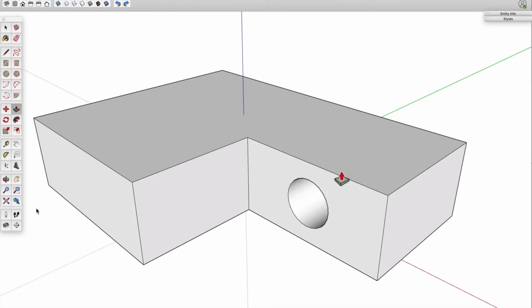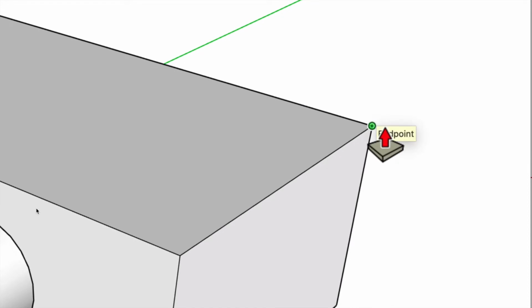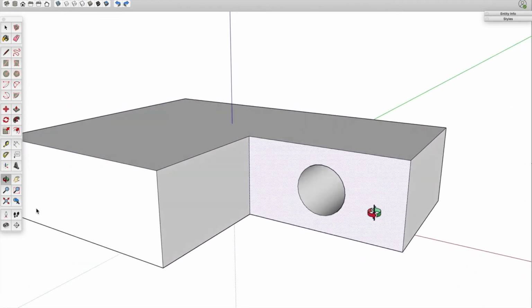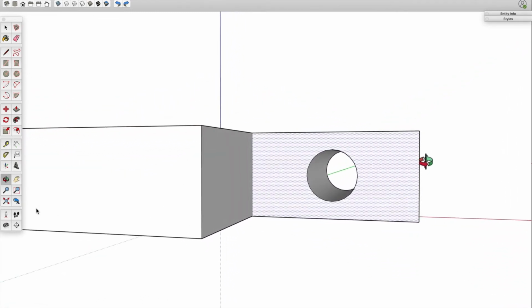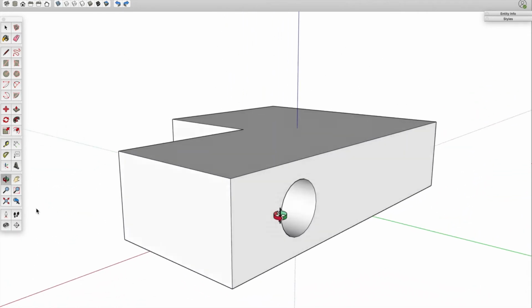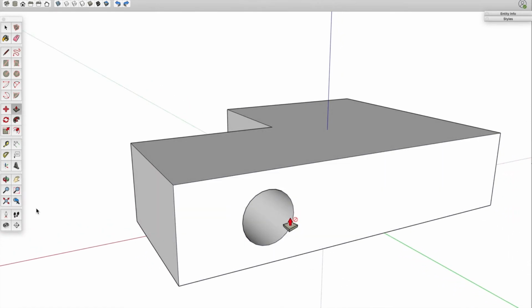So how do we get a tunnel that ends on the other side? Well, you can move your cursor over to this outside corner endpoint to infer it and click on it. That finishes your push-pull through to the other side. And as we know, this flat surface, when push-pulled to the other flat surface, if you go ahead and orbit now, it canceled it out. So now you can see through, or if you orbit around to the other side, you can see that the push-pull happened all the way through and created a tunnel with this cylindrical surface inside.